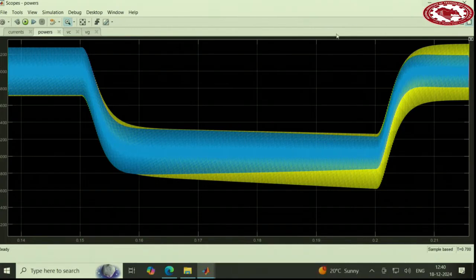Actually, whatever value of inertia you have chosen, it will give you the response accordingly. It will absorb some power. It may have to release the power. But the virtual inertia is in the control itself. But the transfer of energy, whether it is consumption, absorbing or delivering, it will be happening from the real system. That's right. From where does this additional power come, whether it is absorption or delivery?